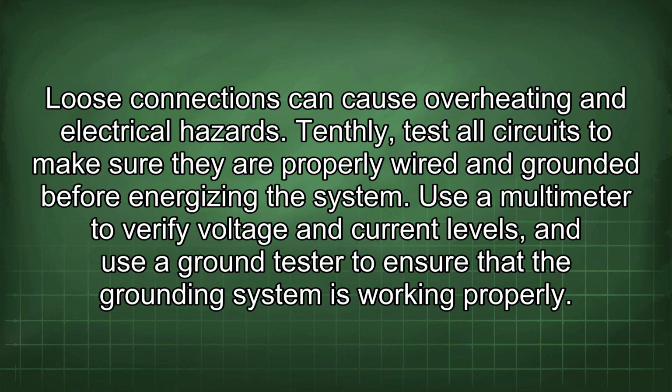Tenthly, test all circuits to make sure they are properly wired and grounded before energizing the system. Use a multimeter to verify voltage and current levels, and use a ground tester to ensure that the grounding system is working properly.